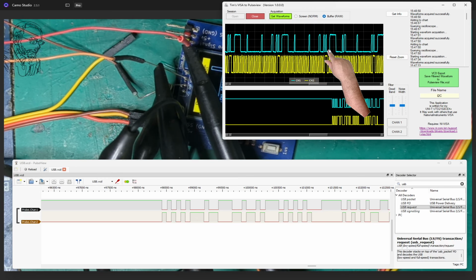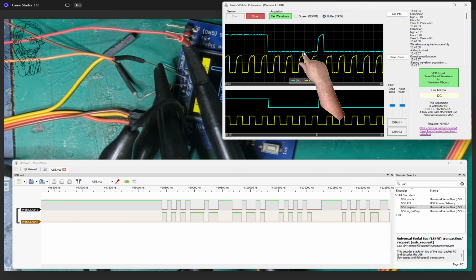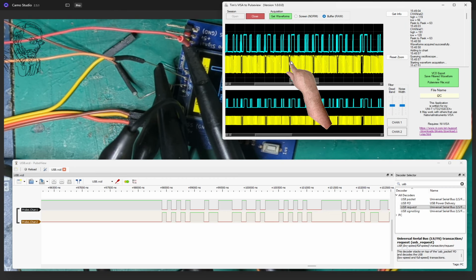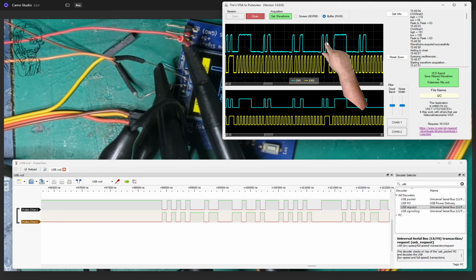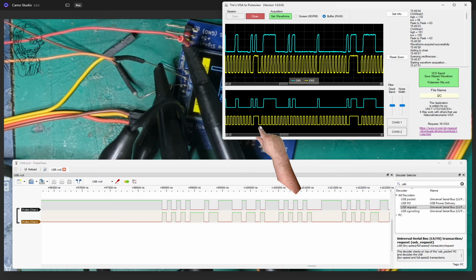So there we go. We've got some data, and we can filter those and see that we've got some nice signals. It's a lot slower as I2C, but basically we've got data across the top and our clock underneath, which you can see when we zoom in. There's our clock, and there's our data. Hang on, let's just zoom in. It looks like we've got three chunks of three bytes there. We'll have our address, and there's probably two bytes of data following. We'll check that.